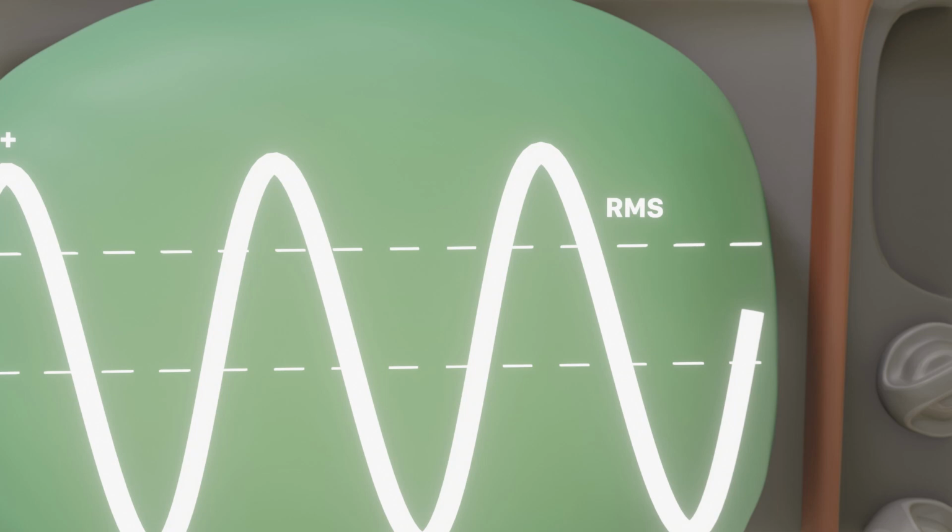For example, the typical 240 volt single phase power that is delivered at Australian household outlets has a peak amplitude of 340 volts. However, as the waveform is only momentarily at that peak value, the effective voltage that any load would experience is only 240 volts. RMS value is also the value that a multimeter would read and is what is used for any power calculations.